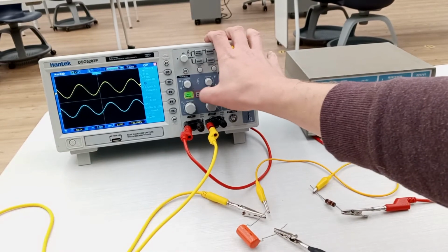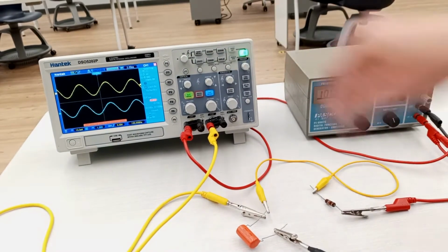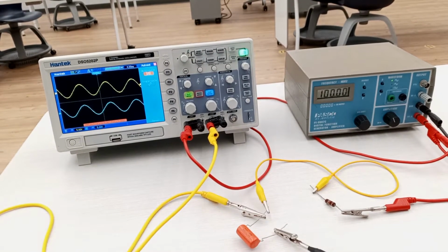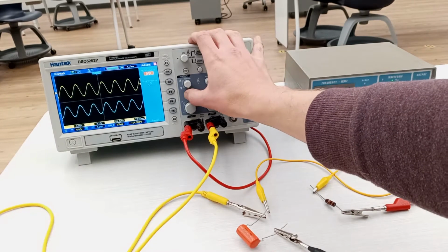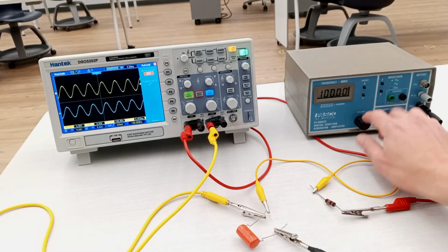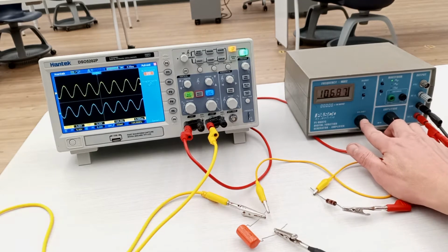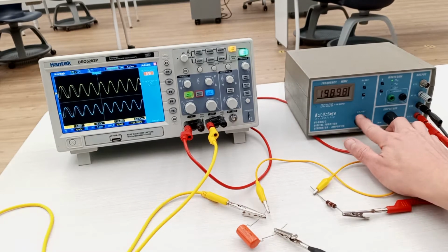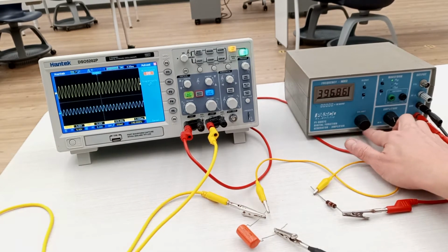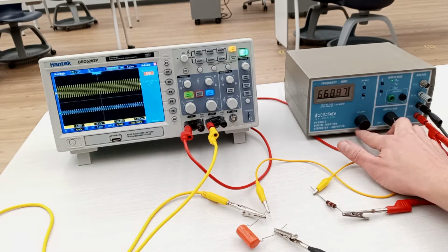Now let's look qualitatively at the frequency domain behavior of our circuit. Because the capacitor takes time to charge and discharge, if the input signal is switching between high and low voltage very rapidly, the capacitor won't have time to reach the maximum voltage. We can see this in the fact that as we increase the frequency of our input signal, the maximum amplitude of the output signal compared to that of the input signal starts to decrease. Because low frequency signals get through while high frequencies tend to be blocked, we call this a low-pass filter.